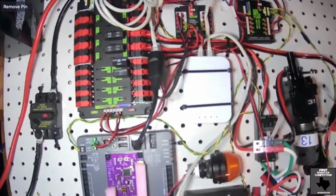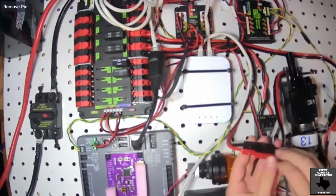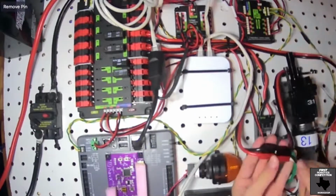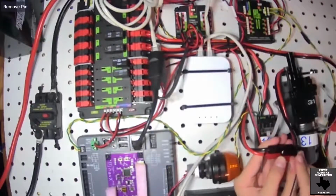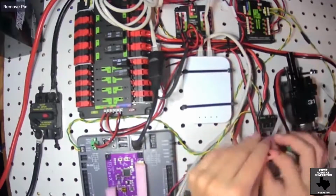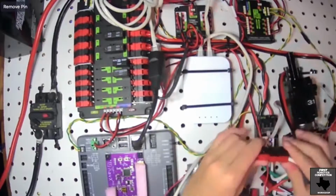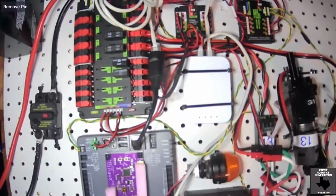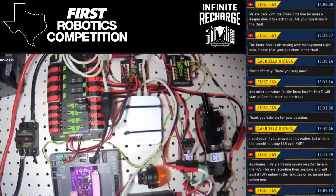Yep. And you put them on the end of your wires yourselves. You buy the little metal contacts that are on the inside and then the plastic things on the outside. It comes in one kit. And then you use a little crimper tool, and I think you can get one at Home Depot. It looks like this. Yep. And then you can put them on completely yourself. You don't have to buy any fancy wires or anything like that. The nicest thing is that you can put a zip tie around it that makes it almost impossible to pull them apart. Yep.